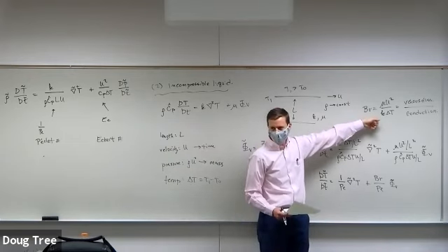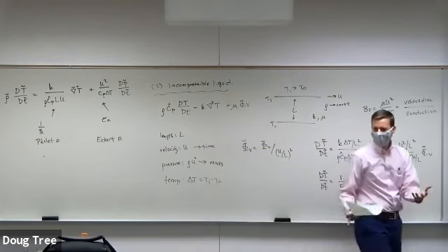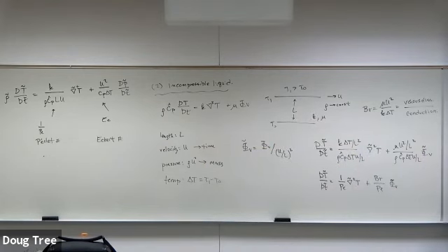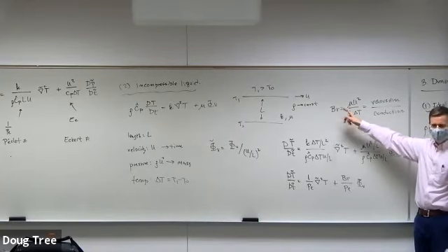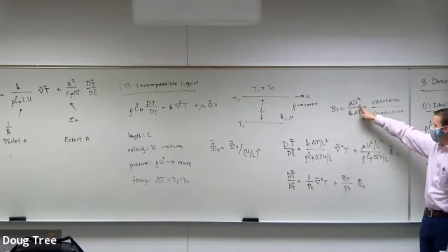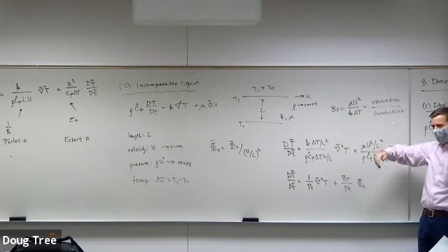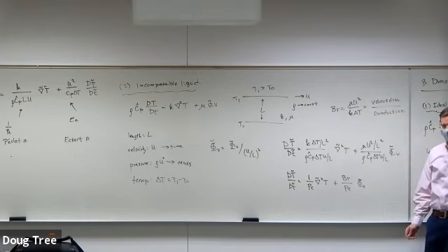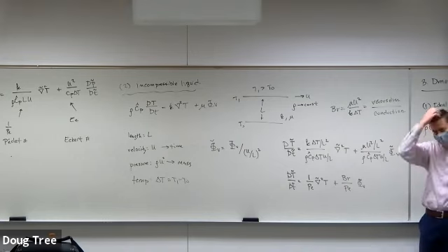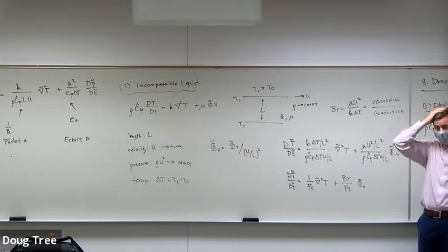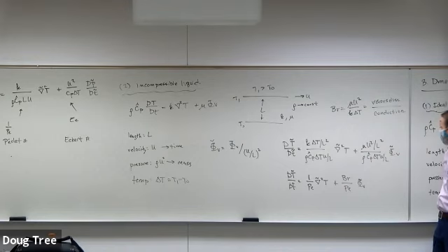I guess we'll just end there, right? So we say, well, when do we care about what's important? He said it seems like the viscosity might be small or whatever. So he's right. If the viscosity is small in a fluid, if I've got something less viscous than water, and u is quite small, viscous dissipation is going to be really low. But if I have something like a polymer, and I'm trying to shear this guy, maybe doing rheology with it, and I'm spinning really fast in a really little gap, then it might matter, okay?